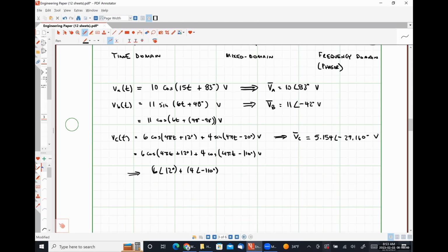Absolutely. So adding or subtracting 90 degrees is giving you two things that are 180 degrees out of phase. So it doesn't matter if you add or subtract 180. It very much matters if you add or subtract 90. So you subtract 90 degrees to go from sine to cosine. You add 90 degrees to go from cosine to sine, which we'll never do, right? Plus or minus 180 is just getting rid of a negative sign. So that's why it doesn't matter which way we go. But to go from sine to cosine, subtract 90 degrees from the phase angle, which is trig identity number 2.